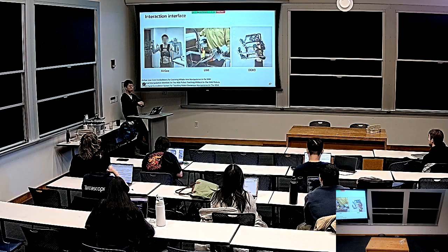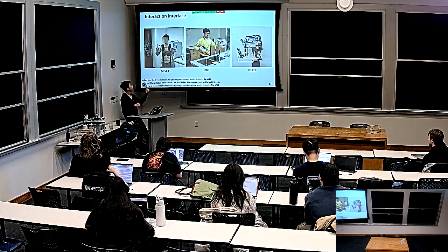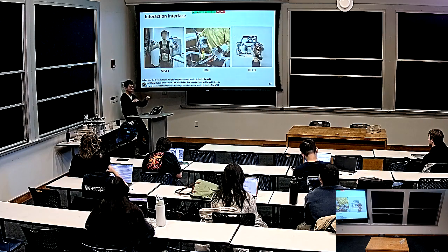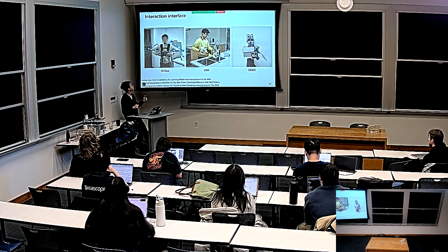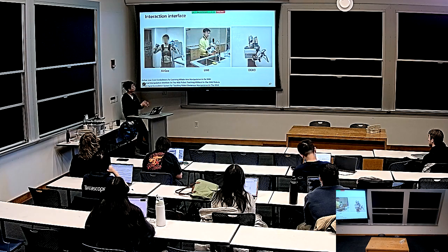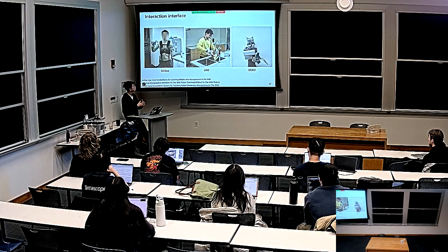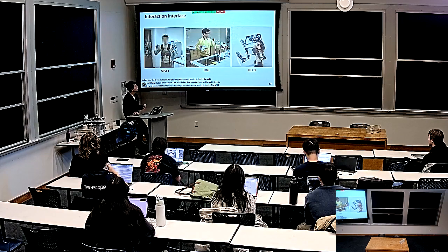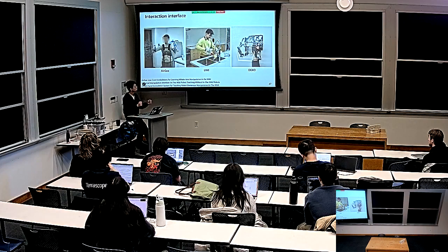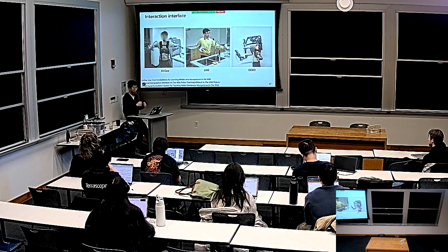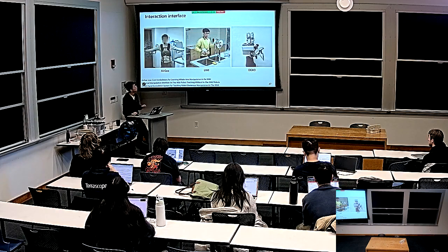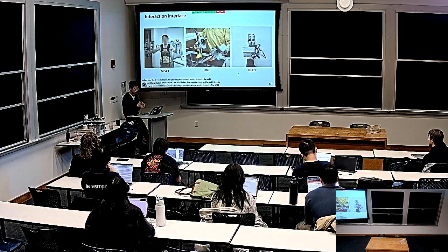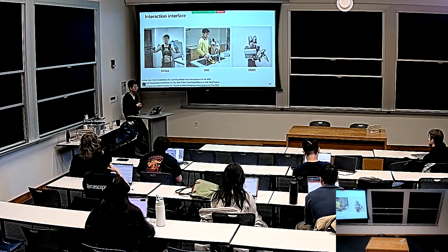It's an exoskeleton that you can wear. On the exoskeleton there are some joint encoders, so you record the robot action. And there are also 2 cameras attached, but you cannot see them from this video. The second one is called UMI, the Universal Manipulation Interface. It's similar: there are 2 cameras attached to the gripper, and they recover action from the GoPro through SLAM.